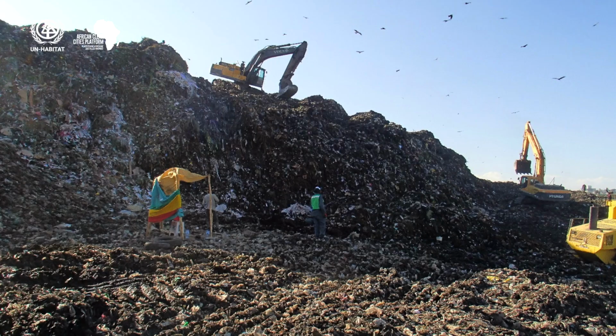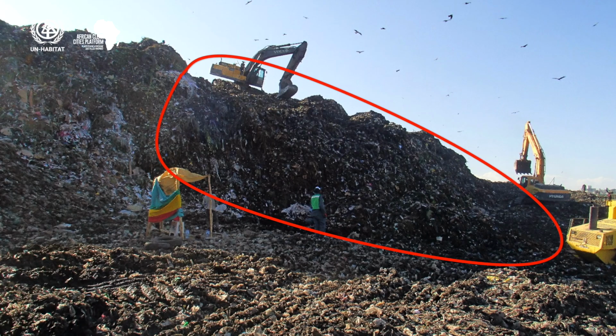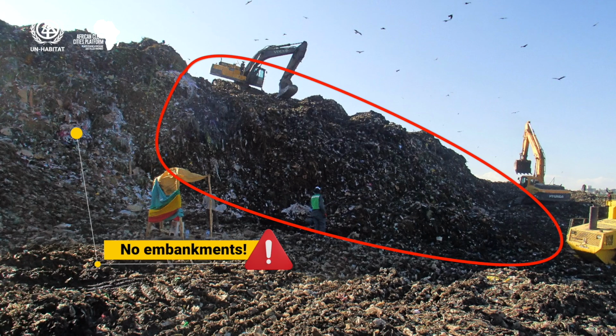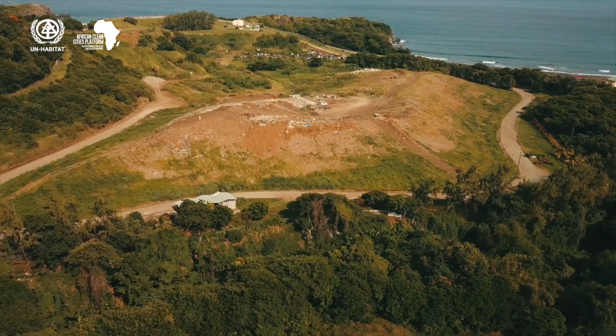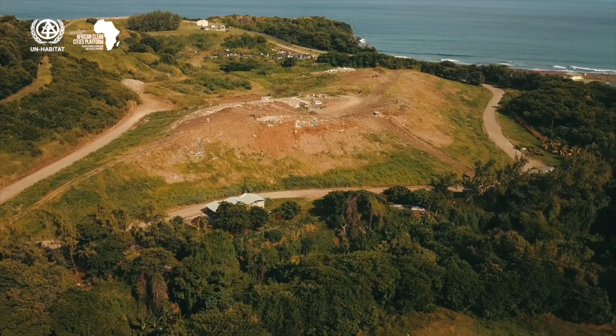Embankments are essential for landfill structure. You can see here slopes at the edge of the landfilling area where the collapse of waste has occurred. This was caused by uncontrolled and unplanned landfilling of waste, where waste was pushed outward without compaction. And nor was there any embankment. So, as you can see, proper embankment construction around the peripheries of a landfill, including good compaction and fine slope arrangement, is critical for landfill safety.